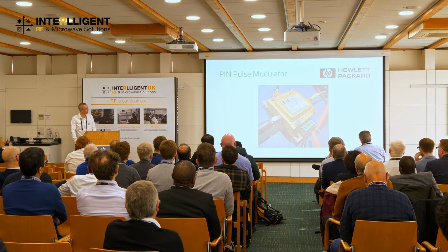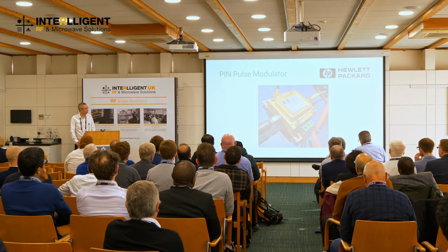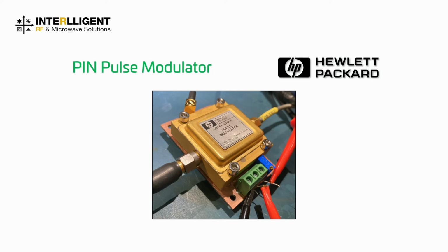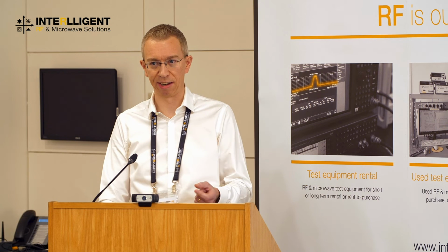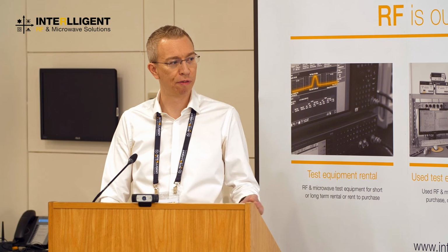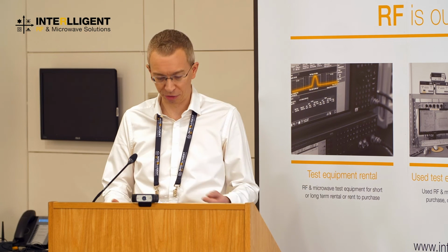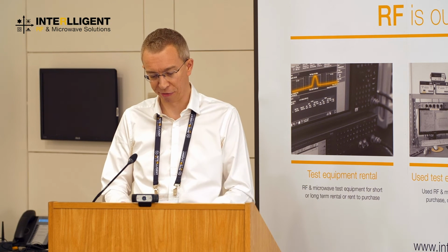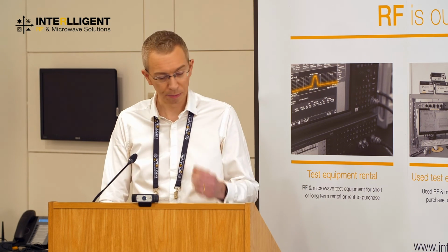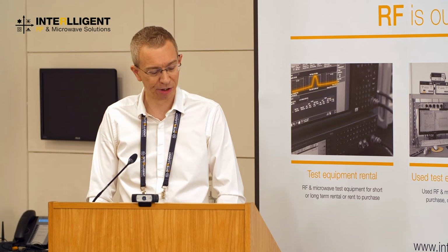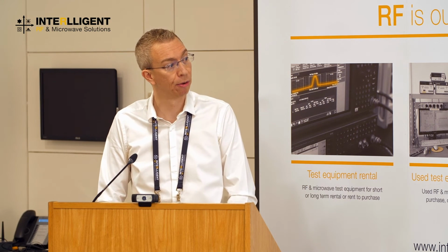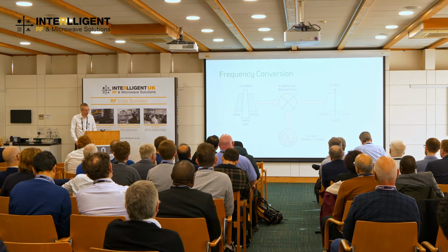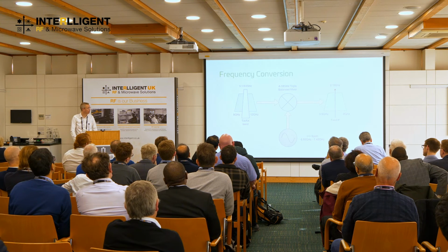They've got 80 dBs of isolation at the band of interest. And we used a MACOM MADR pin driver. These are great. It's an SO8 IC that is a complete driver for pin applications. Anybody that's had to deal with that will know often it involves quite a bit of circuitry to be able to switch bipolar voltages fast with very little latency. These chips are hard to beat in terms of price, real estate and performance, so that's what we use to drive it.